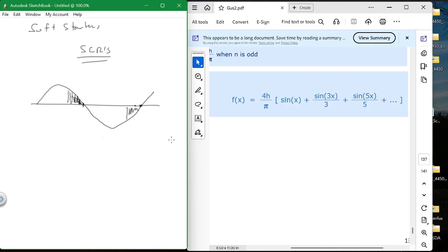All right? So one of the guys got this bright idea, well, I'll just use a soft start instead of an inverter. So you save money if you run it at 40 horsepower. Okay. So originally they ran it with DC motors, 40 horsepower DC motors, but they would run them slow. And then when they got up to 400 degrees, they increased the speed up to the regular speed of the motor, and then it worked. But DC motors have an inherent problem in that they've got brushes and a maintenance issue. So you don't want to do that, and they cost a lot of money.